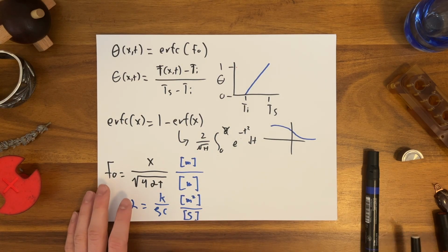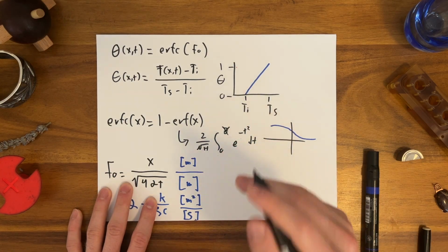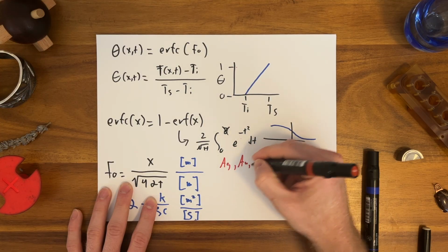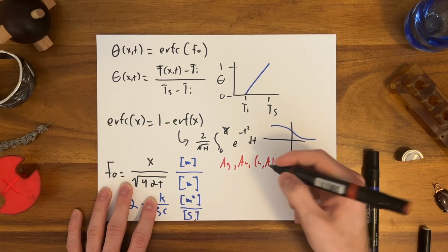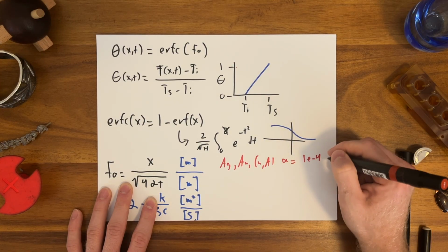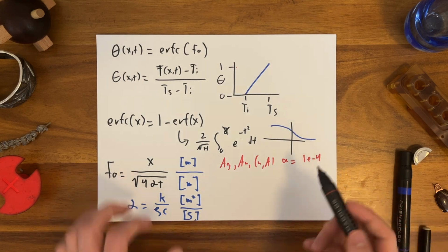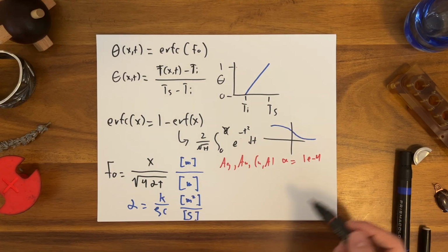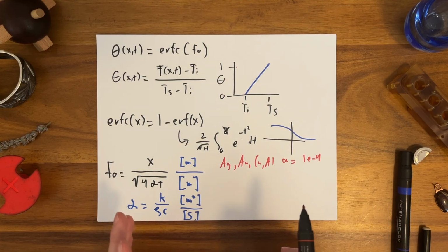It's actually quite easy. If you are a shiny electrical metal, if you are silver, gold, copper, aluminum, your diffusivity, alpha, equals 1e minus 4, within a factor of 2. Like a nice pure silver is twice as high, and a dull aluminum alloy is half as much, but a factor of 2.